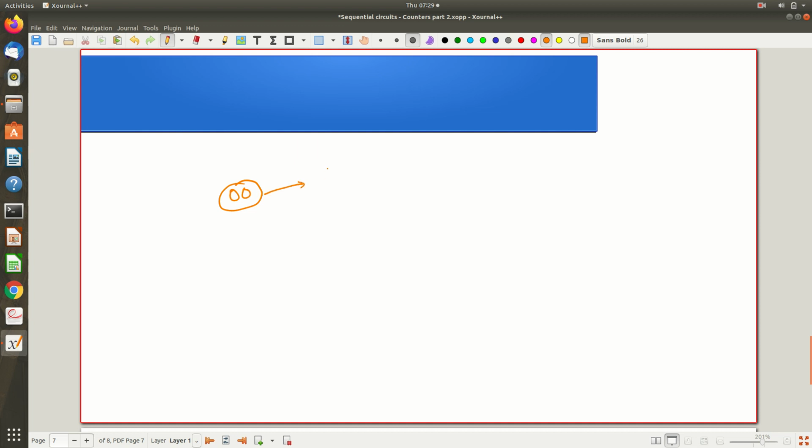You can now draw this. For that, what I am doing is 0 0, this is your Q1 bit and this is your Q0 bit. At every time this Q0 will toggle. Now during this toggling, Q1 is also supposed to toggle because Q0 is changing from 0 to 1, so Q1 is supposed to change, but that change will happen after some time. Still it will retain that 0. After some time it will change to 1 1.